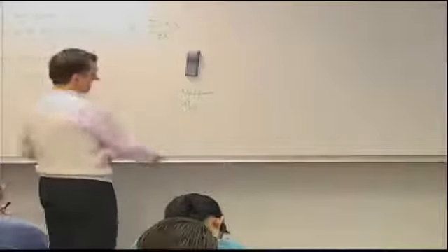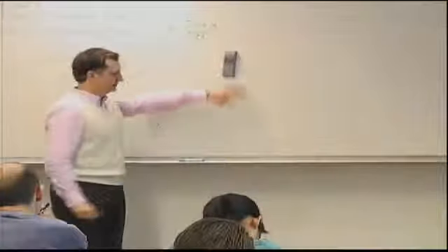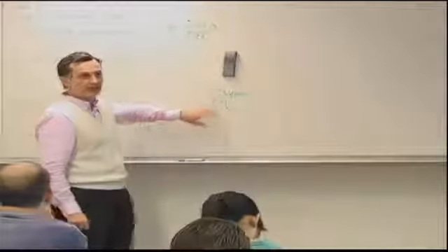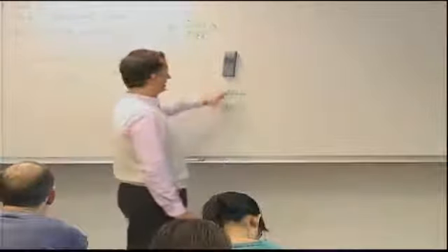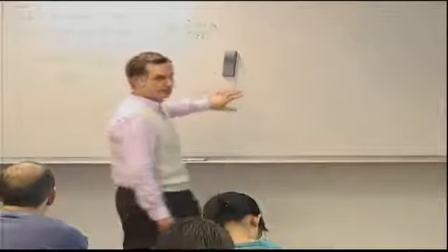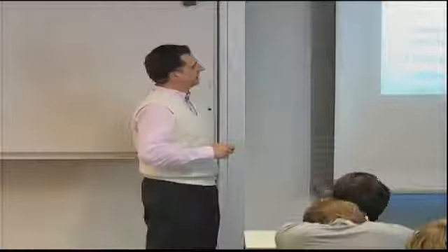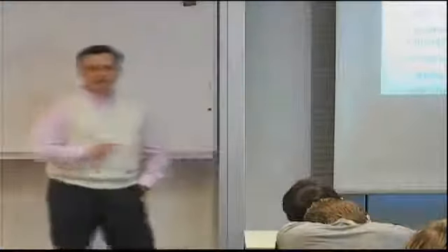And as long as the EA of the stiffeners is 10 times or something like that bigger than the EA of the skin, then it's a safe bet that most of the load goes into the stiffener versus the skin. So this assumption is a good assumption, especially for a quick calculation that we're trying to do here.